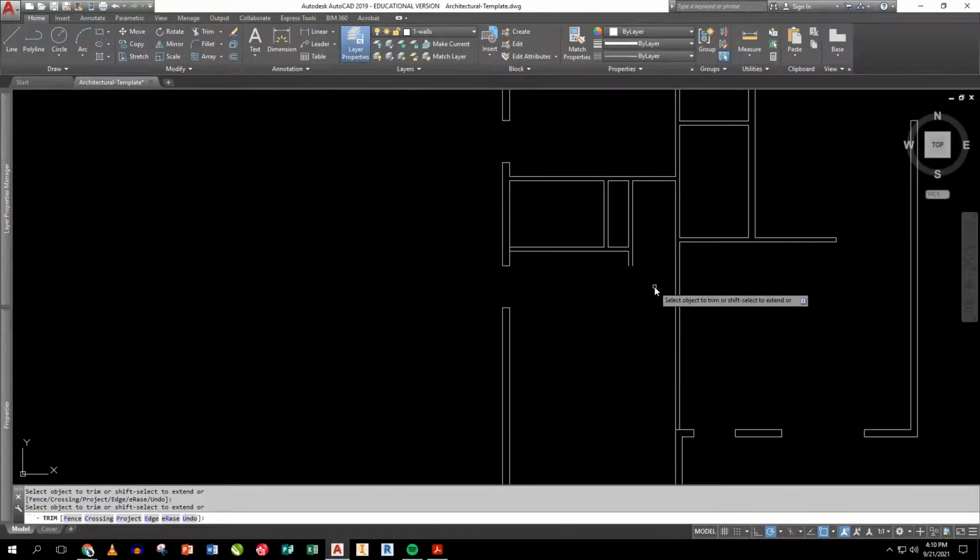So there is my closet, my master's little walk-in closet, and this is where the bath is going to go in this hallway. And again, it's 5 feet across this bathroom. Well, in that case, just go offset 60 inches, which is 5 feet, from here down. Okay, now this is going to be a plumbing wall on this side, so I'm going to offset 5.5 inches for the plumbing in that wall right here.